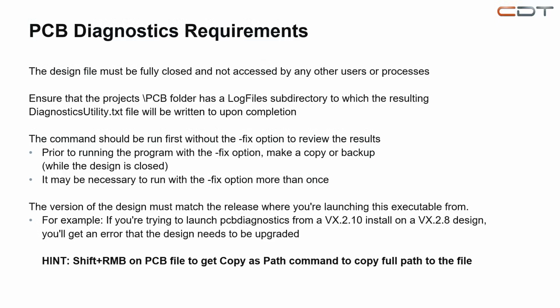First, you need to run the command without the fix option to review the results and understand what's going on. Of course, as usual, I suggest you make all these fixes on a copy of your design, not on the original one. It might be necessary to run the fix option more than once, in a couple of shots.